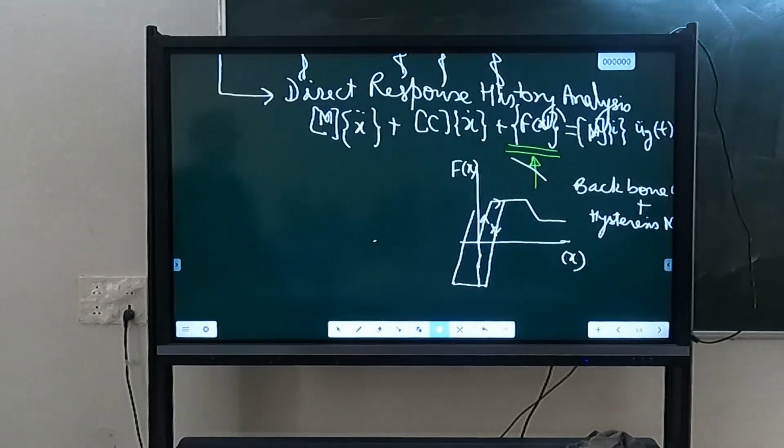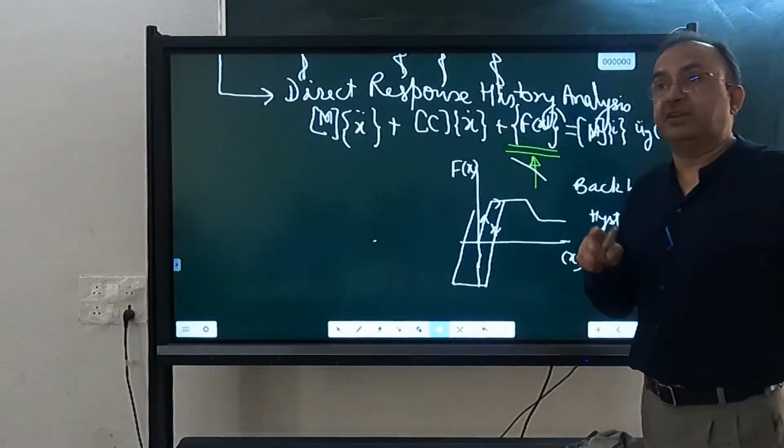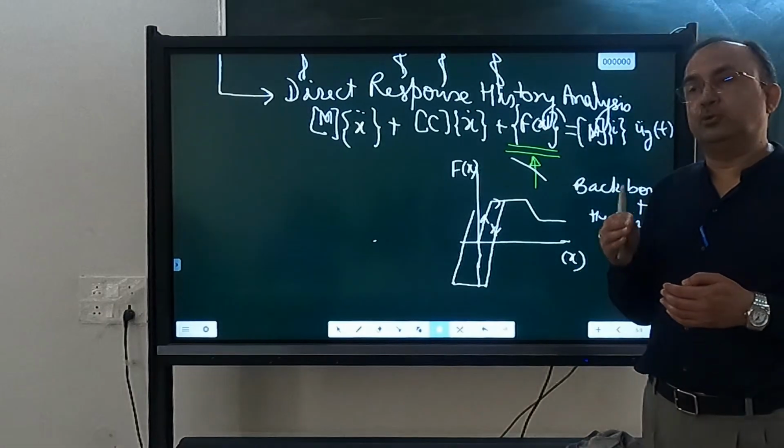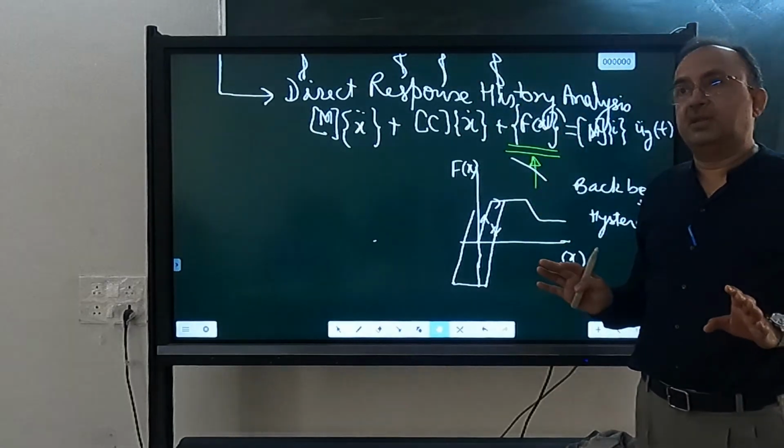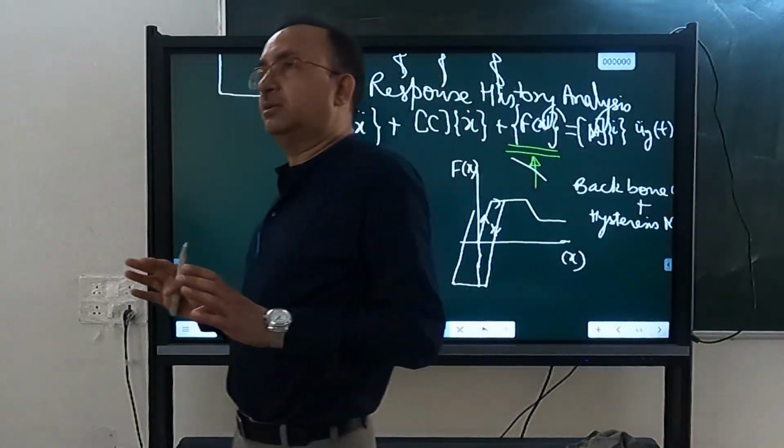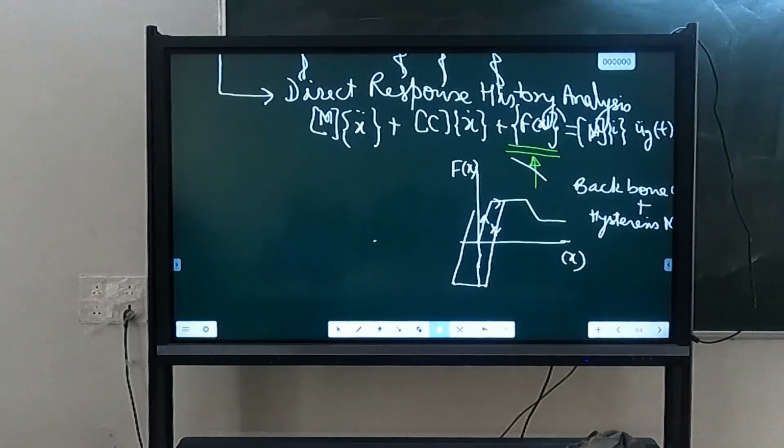So, more than the strain rate effect, strain rate effects come into picture generally for strain rates higher than earthquake. The type or the range of the strain rate which are applied during earthquake, the effect of a strain rate is negligible. You can ignore it. Problem is not the strain rate, that actual force is applied at much higher speed and we are applying slowly. That is not a big issue. That will be an issue if we are talking about blast loading or missile impact. There, that problem will be more significant. That is not our main worry.